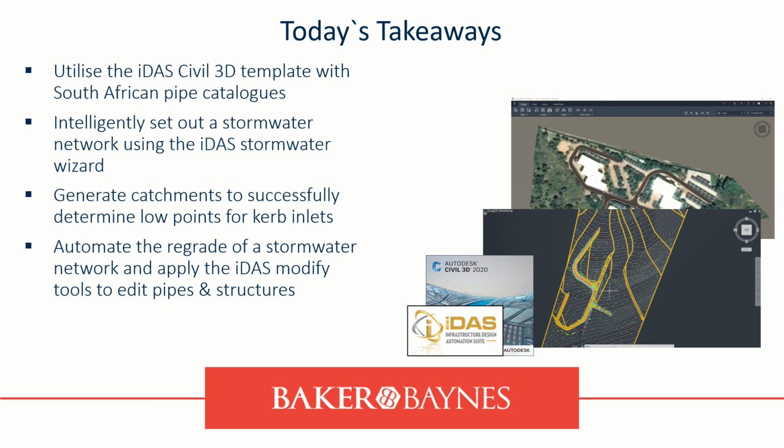So this is what we did. We did the InfraWorks model on the right there, as you can see. We imported into Civil 3D. We generated the catchments. We figured out the low points. We dropped in the curb inlet positions with those circles. We drew in the polyline. From the polyline, we checked the directions. We used the map cleanup. Then we did the network. We created the network. We swapped the structures, and we created the labeling.